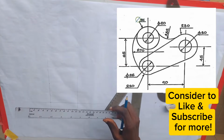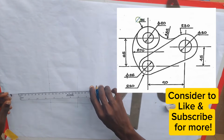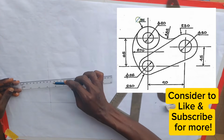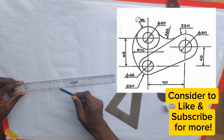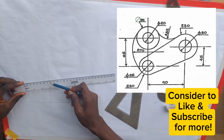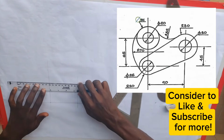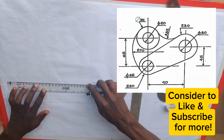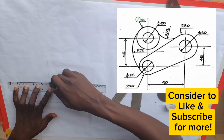Now, in case you don't have T square, you can make use of ruler. I will teach you how you can use your ruler to draw a straight line like this. Always use this 10 and 8 in your ruler. Why? Because you see that the line of 10 and the line of 8 here, they match the same. That is, they align with each other. If you look at others, the line of 8 here and this one does not match. But we always use 10 and 8, as I've said. So I will place it here because I want a straight horizontal line. I will make sure that the 8 and 10 line match with this line, just as you can see here. So I will draw a straight line like this.